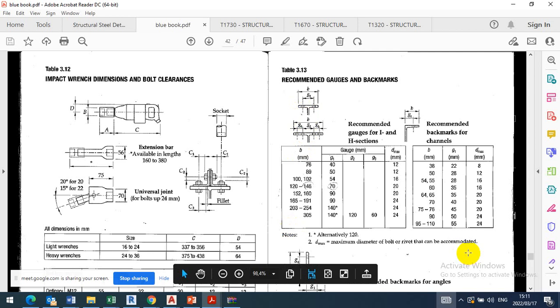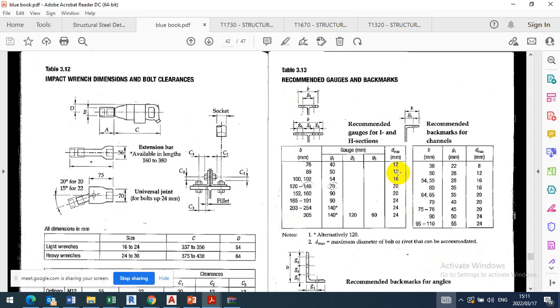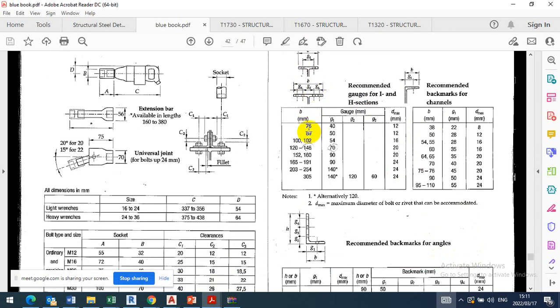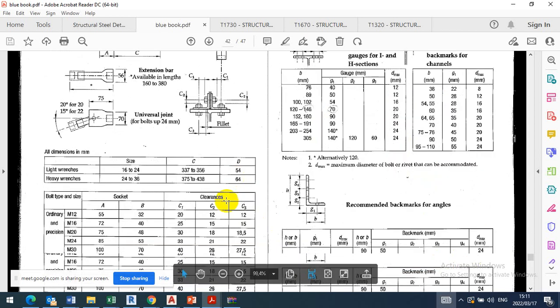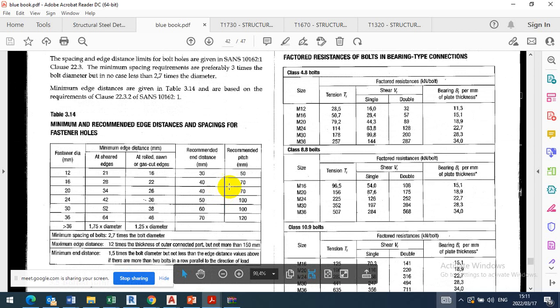Okay. Which one did you want? This one? I was just looking at the plate, and that plate doesn't make sense for me because it's way too small to carry that type of. Yeah, it's fine. As long as you have calculated the center of the holes, and the edge distance is correct, like minimum, like I told you, that is what they are recommending. And then according to this size of the bolt, it won't shear off. Because if we go to the bigger ones and where there's a lot of force, which we call the shearing forces and all that, then you must go to the bigger size.